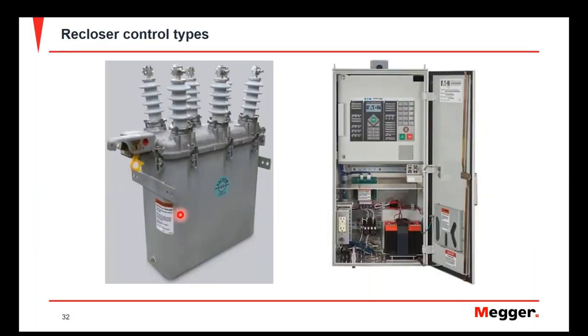So here are some control types for reclosers, and typically you're going to see either a hydraulic means of controlling the recloser or an electronic means of operating the recloser. Now, the hydraulic means is a majority of it is seen on single phase units, and these type of control units operate through a means of an overcurrent trip coil that is in series with the line that's going to the recloser.